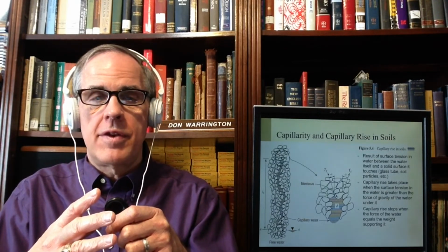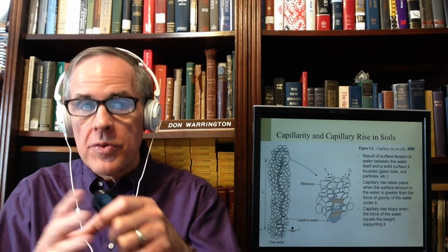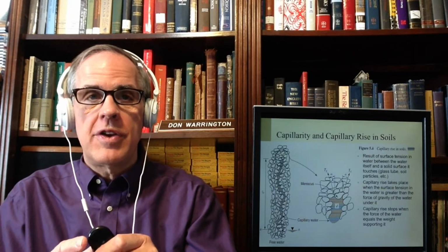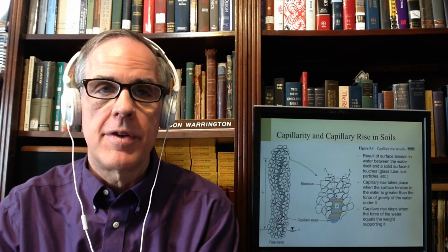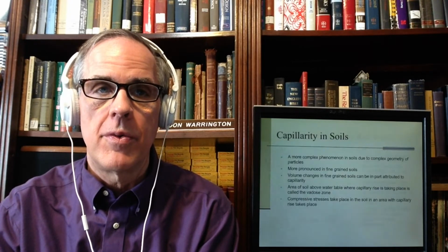Now, that doesn't necessarily mean the void ratio goes down. What that means is that the voids are smaller. It's just that with smaller particles, there are more of them in a space. But generally speaking, as particles get smaller, the voids get smaller, and you get more capillary rise because those voids act like a tube to pull the water up.